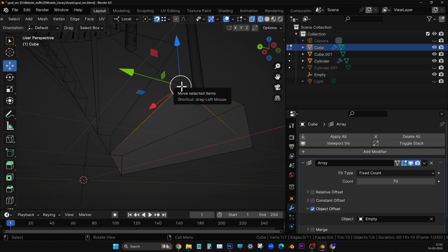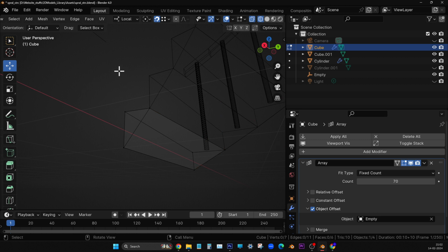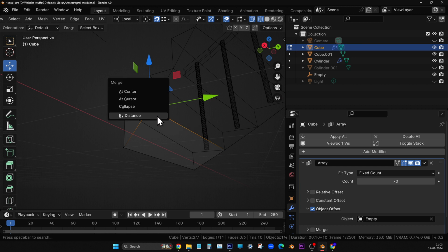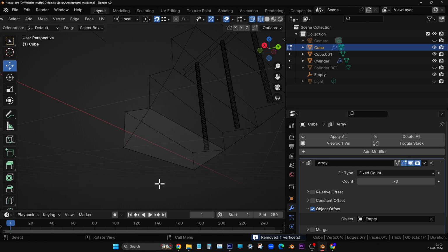Whenever you are selecting a single one, then we take the cursor there and pick selection. Right. Now this side also I have to do the same. Alt A, deselect everything, have a fresh selection, draw a rectangle, press M, and then By Distance 0.01. Yeah, it's already applied.